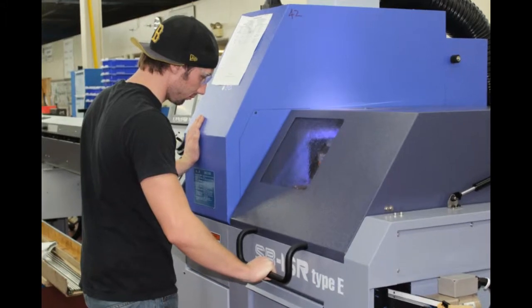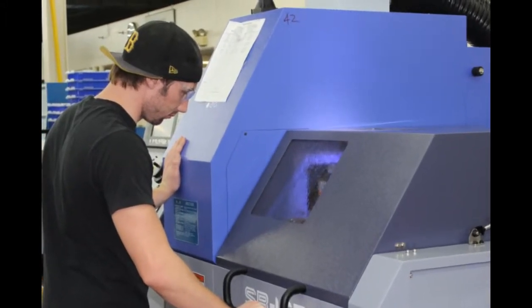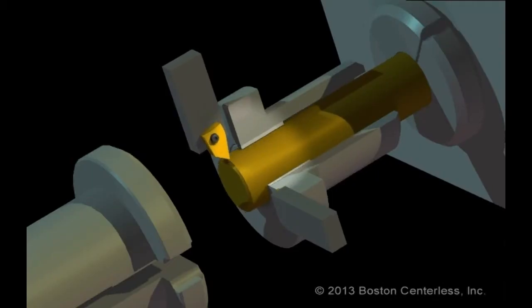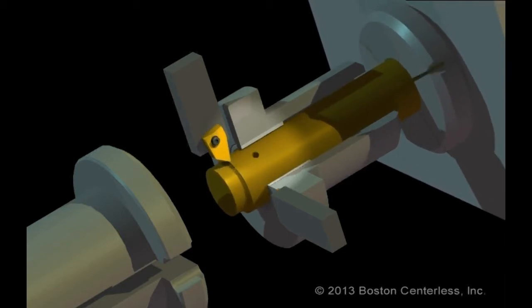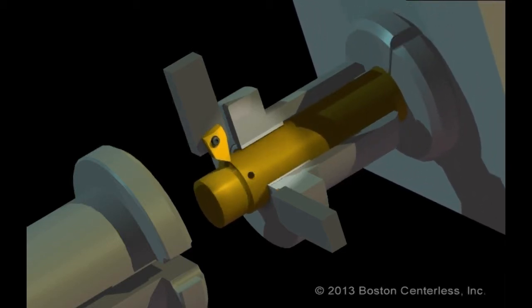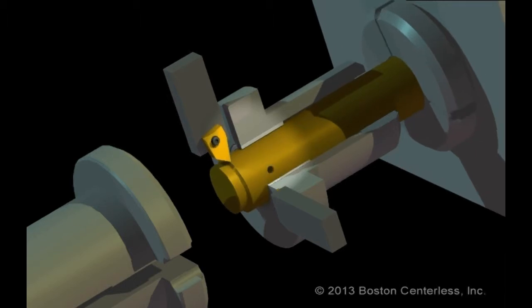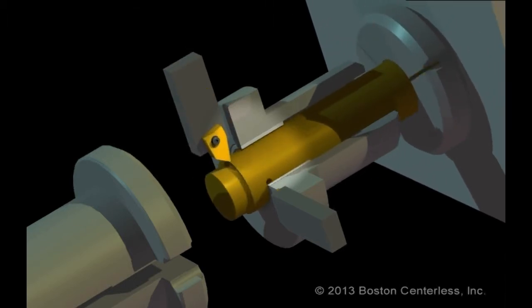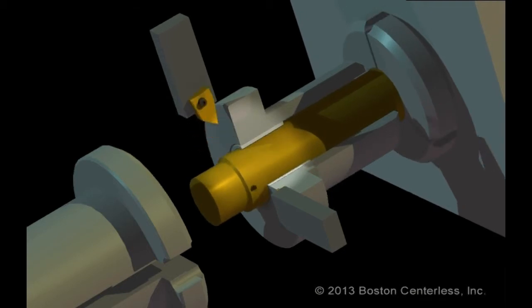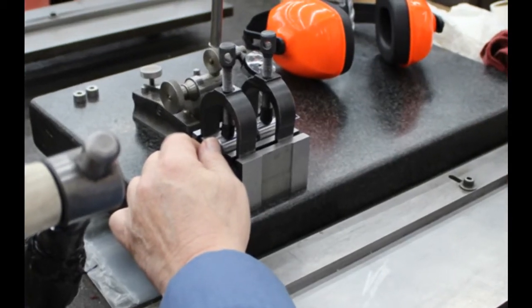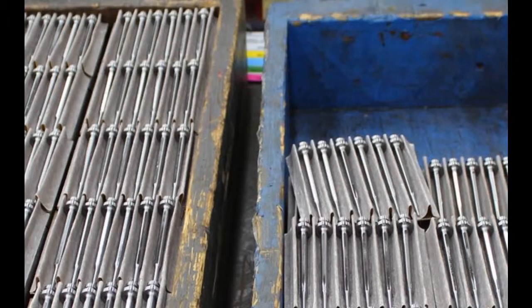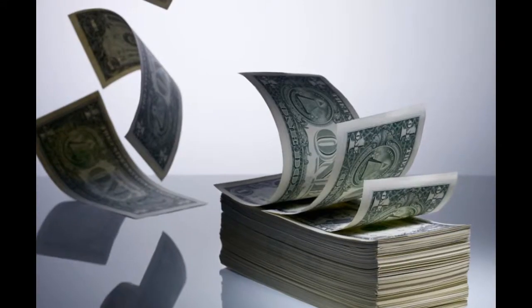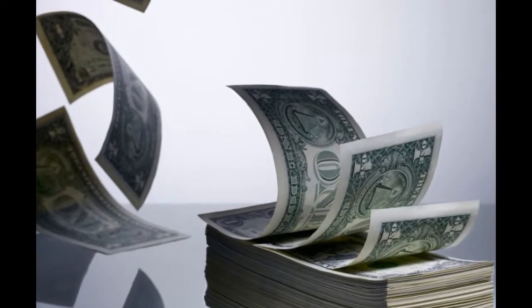When this happens, the operator now has two choices. He can slow down the machine to keep the vibration frequency away from the machine's natural frequency, or he can continue operations, potentially speeding up the material to get past the machine's natural frequency. But doing so, he runs the risk of making bad parts which may later need sorting. In either case, your costs increase.